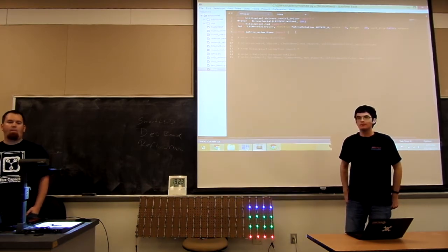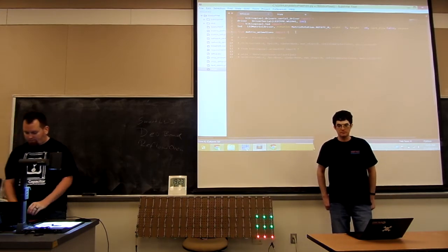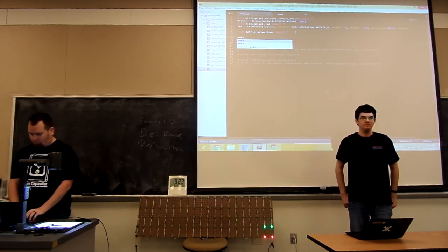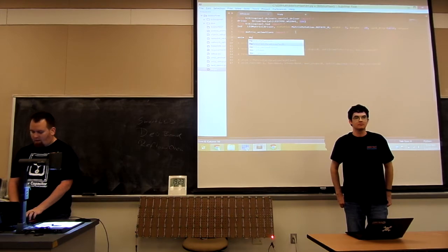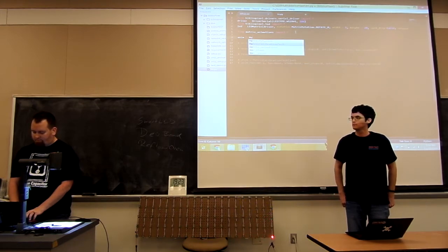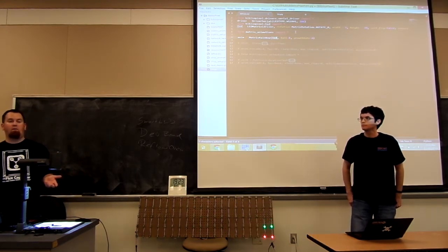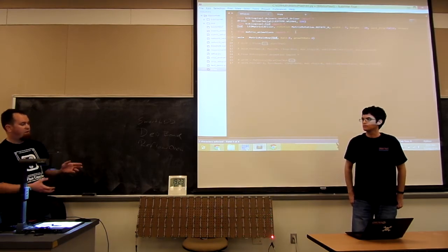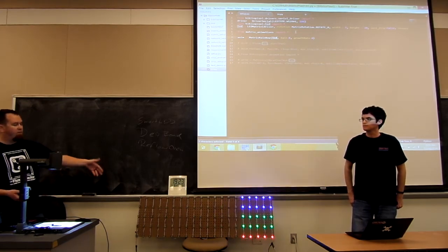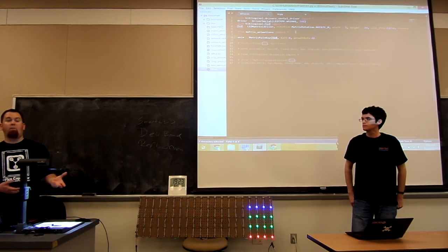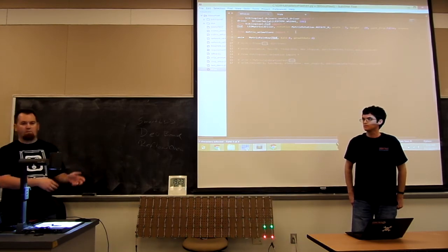So you're addressing each LED, each LED then has an address, which is part of the packet. You set up a buffer of bytes, isn't it? Yeah. It's a shift register, is really all any of them are. You shift enough. So with these, since it's 1 chip per LED, you shift in 3 bytes. The next time you shift another 3 in, it shifts those to the next one.